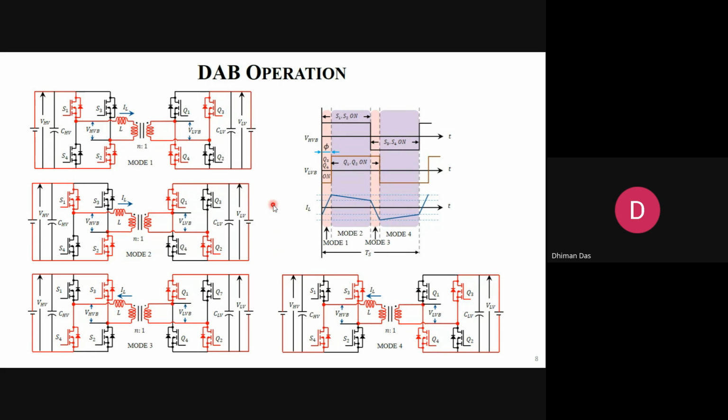If you're using any monitor or anything, all of this can malfunction because of this high DIDT. It acts like an induction oven. In an induction oven, a flux is generated, and this flux circulates inside your pan to generate the heat. But in any power converter, this kind of phenomenon is always generated.